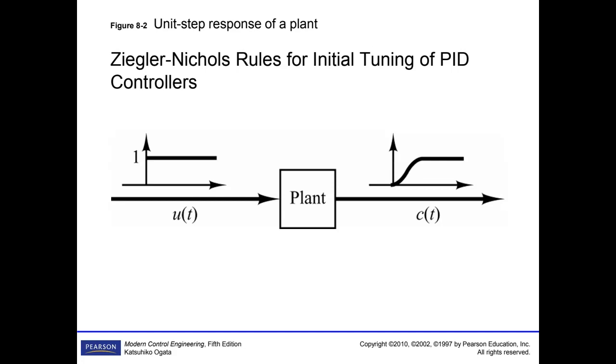If you have an output like this, that means either your system is second order, third order, or however, its damping is heavy, therefore no oscillation occurs, or it is a first order system. If you have an output like this, then use the Ziegler-Nichols first method.